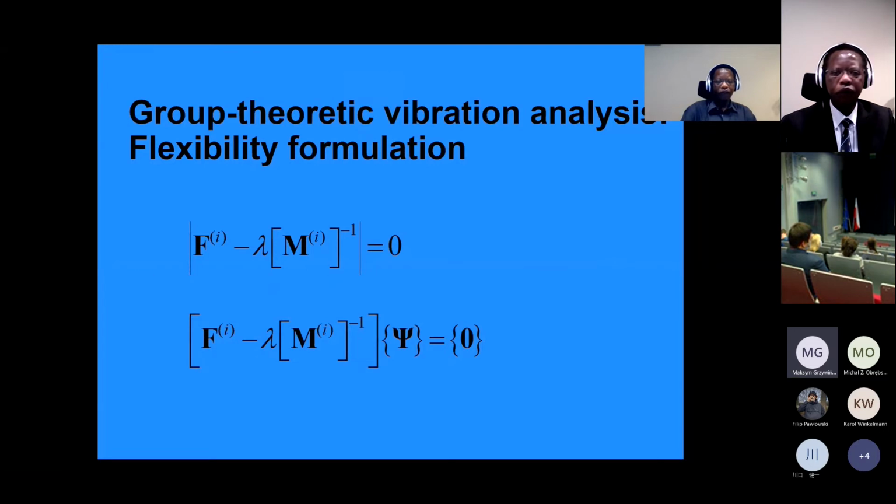The subspace eigenvalues are also the eigenvalues of the original problem. In this way, all the frequencies of vibration of the system are obtained. The second equation allows the subspace eigenvectors to be evaluated by substituting each obtained eigenvalue into the equation. Subspace eigenvectors are, of course, Ri-dimensional.